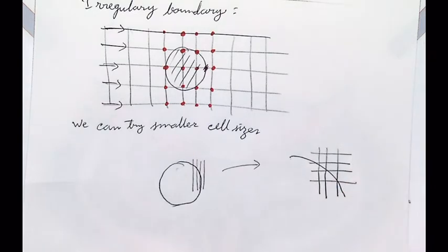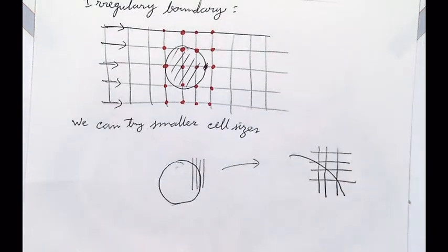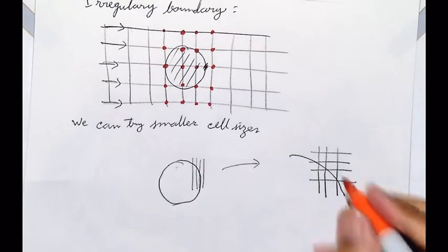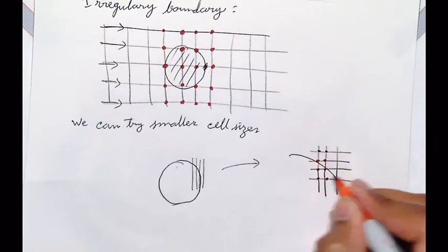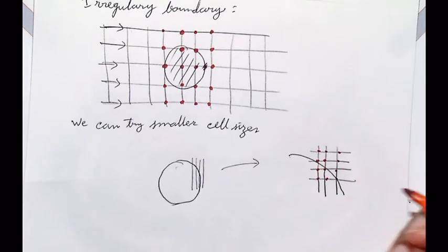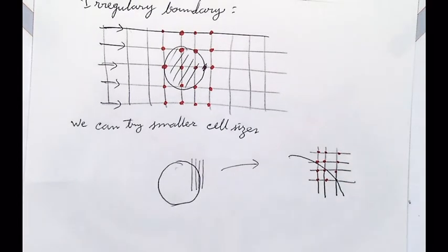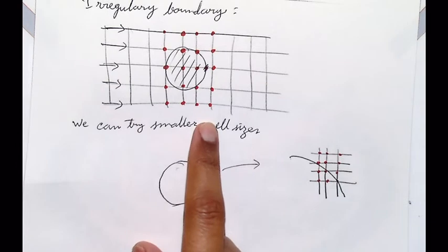Did your problem go away? No, we should define a curvature function for the wall. It doesn't remove it, of course, but the error will be reasonably small, so it's much better than a coarse mesh.